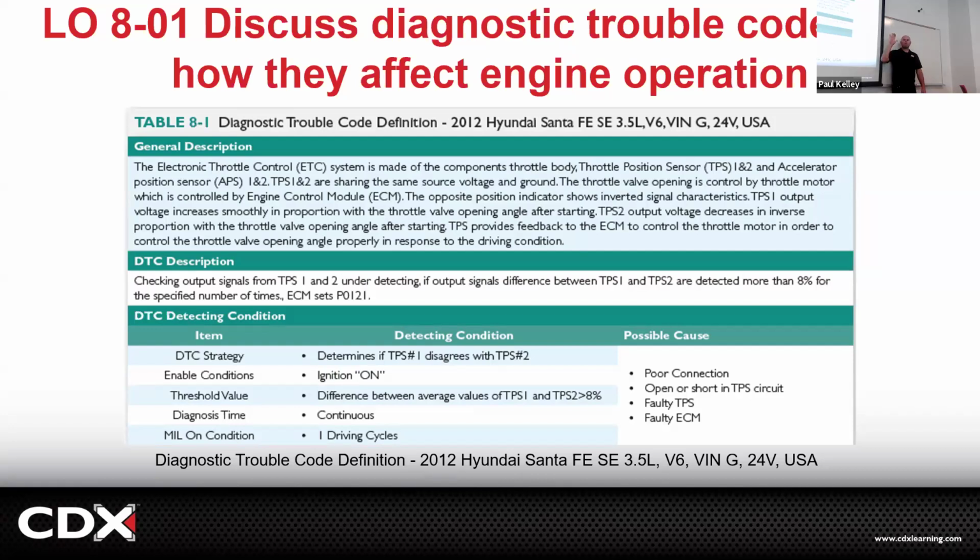So if you put your foot on the gas, then you let your foot off the accelerator pedal and it reads 0 and your throttle still reads 50, what's happening? The throttle's stuck open. That's a big safety hazard. Boom, shut it down. Kill the spark, kill the fuel, kill everything. That car's not going to run away. No way, no how. Cool.